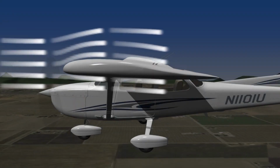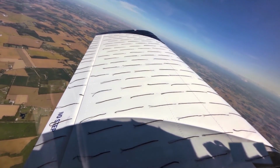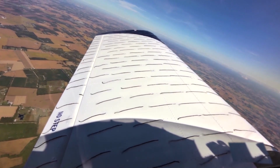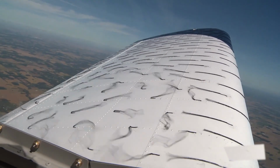Another example of a very dangerous stall is the tip stall, which can cause wing drops and reduce the control over ailerons, which help control rolls. This type of stall is more common in airplanes with tapered or swept wings.